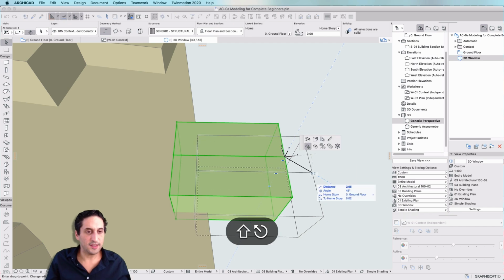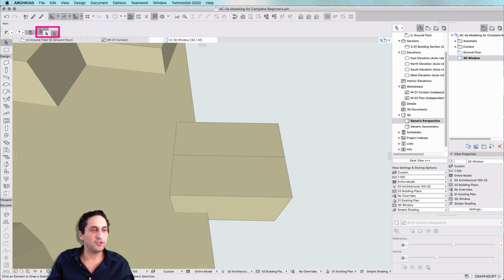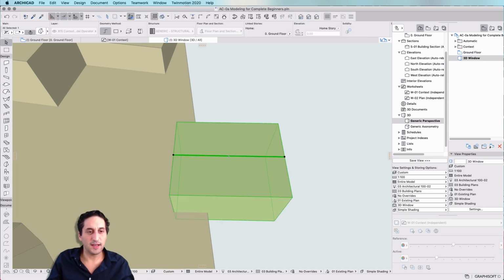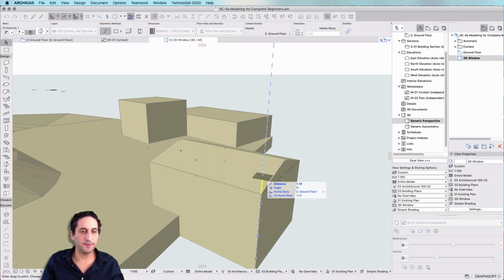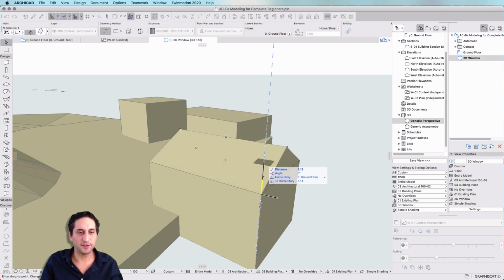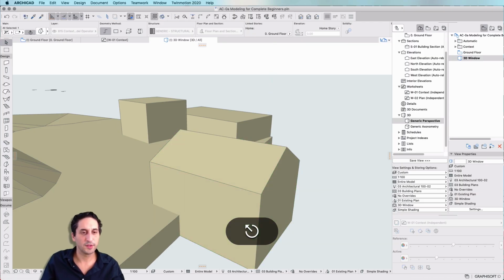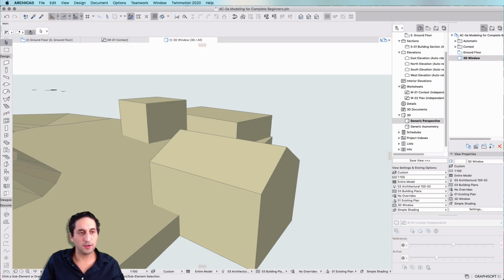You got it. This allows us now to change to sub element, select that particular edge and start the drag command, command D, pick up a reference point and then move it upwards as high as you think it would look good. Now you repeat these on the other three.